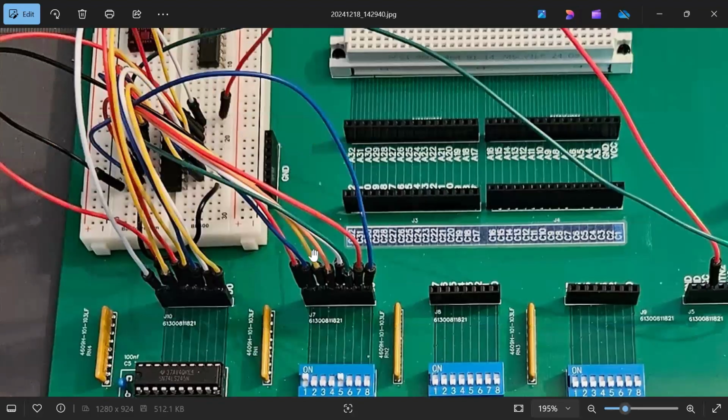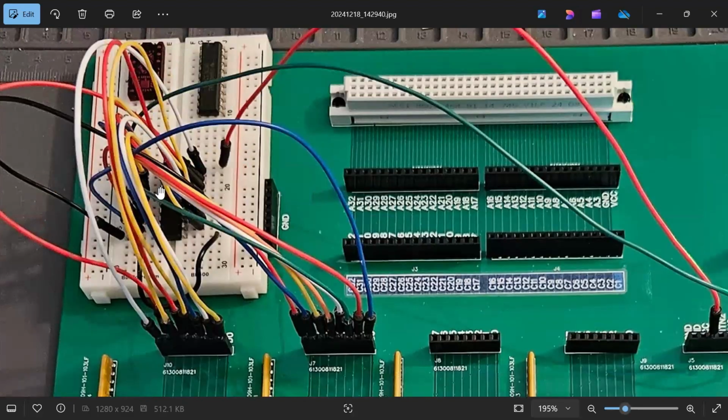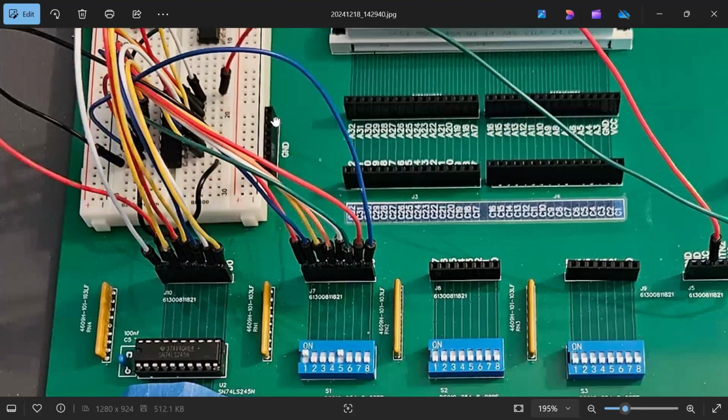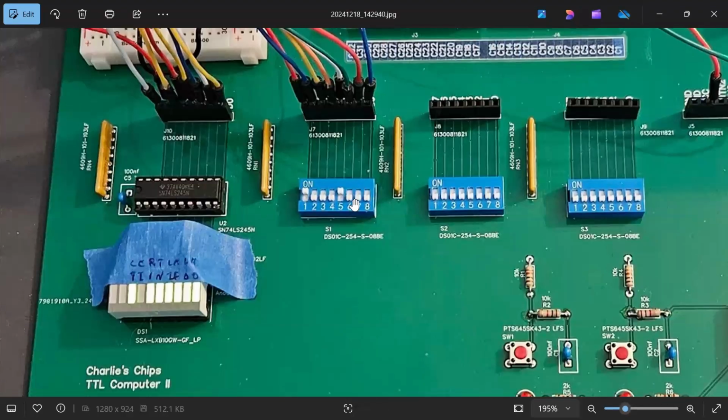So what I did was I moved these wires. I moved one of them to be on the outside edge of the breadboard, and I moved the other one on the inside edge of the breadboard. And I did the testing again, and that cleared up the situation. So it looks like it was just a signal bleed over from the breadboard, basically an issue in the breadboard signals.